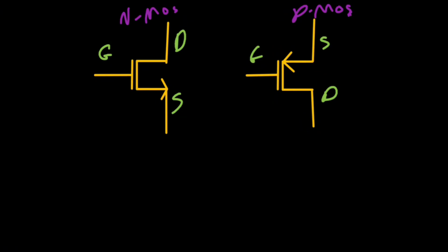for this course is to create a complete 8-bit working computer using simple transistors. Everything in the digital world is created using transistors, and the only thing that you need to know about them is that transistors are simple switches. We have two types of transistors, NMOS and PMOS. Each one of them has three terminals: gate, drain, and source. I of G, or the current through gate, is always equal to 0.